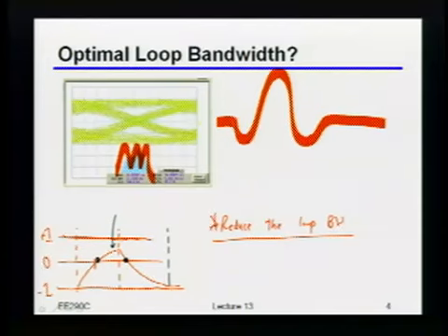Because even if I sampled this point late, because this was late, I had already run into the next bit. And I would actually have worse timing margin than just sitting at the nominal spot that I thought I should have been at in the first place. In other words, if I just always sampled right here, that would be better than trying to move the sampling point because this earlier edge was a little bit late.